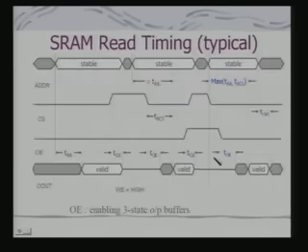Now let us look at this timing in more detail. So this is a typical scenario where I have also assumed that there is, at the output stage, a buffer, a 3-state buffer. So one of the states is a tri-state high impedance state, and I have got the output enable signal which enables the output buffer. So here we have got more timing parameters which I have shown in this context.